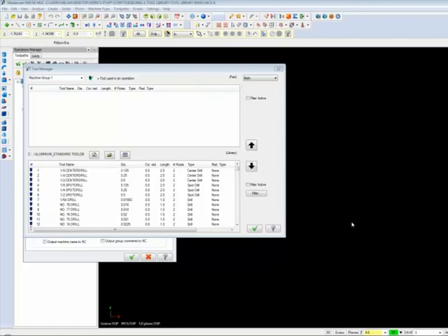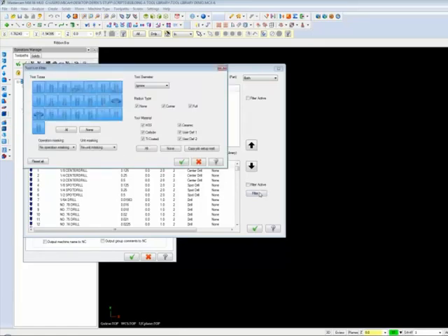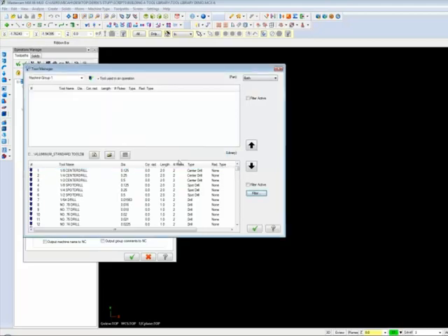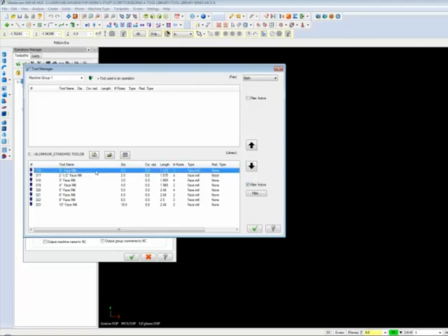The first tool in our permanent tool library will be a 2-inch face mill. Click the Filter button, deselect all filters, then select the face mill button and click OK. Click the Filter Active box above the Filter button to display just the tools we set the filter up for. Select the 2-inch face mill, right-click, and select Edit Tool.